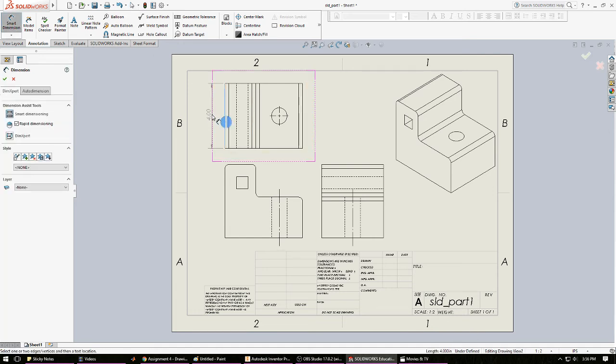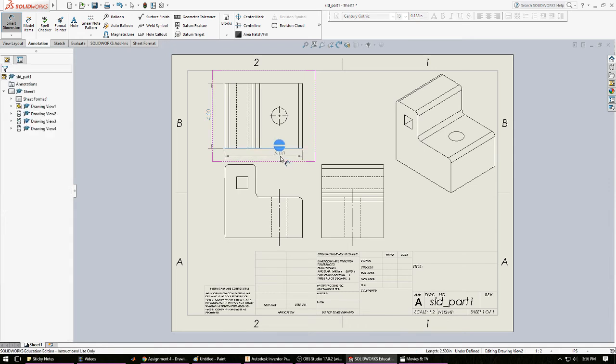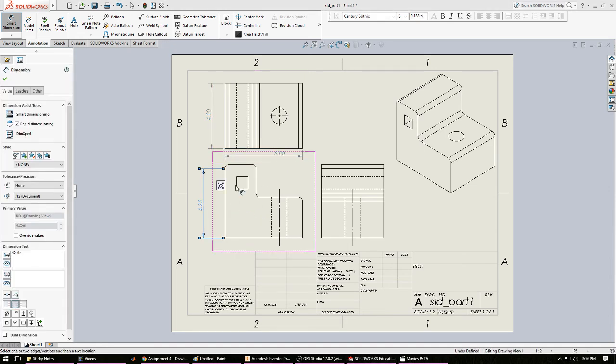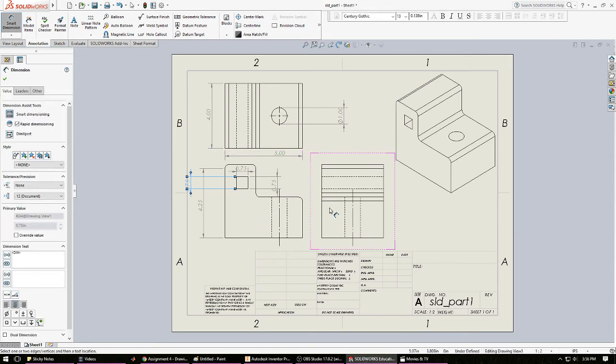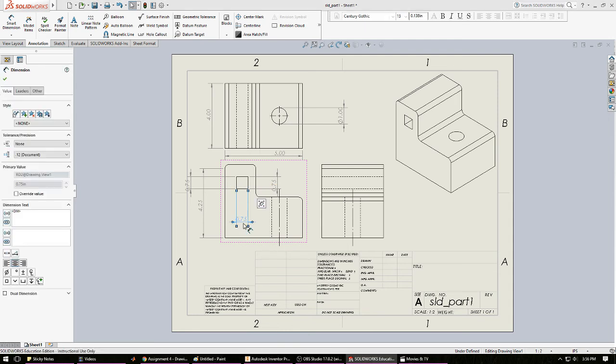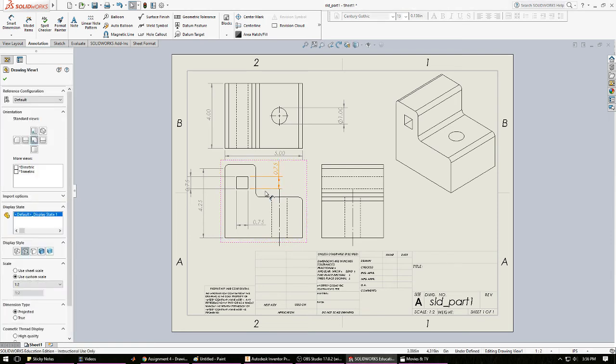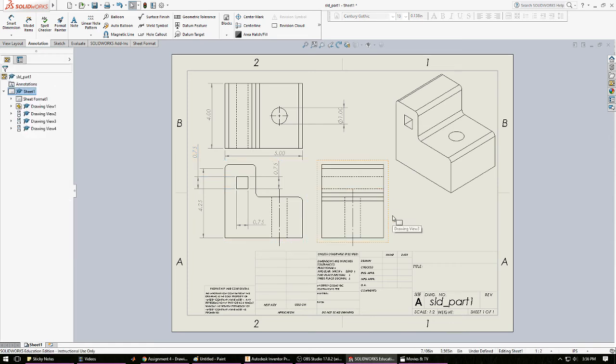So you just click Smart Dimension and you start adding stuff in. You can do overall height, length and width. You can add all these things in that we would expect you to do. Something like this. Obviously, I'm putting them in ugly locations. One thing about this is presentation is key. If this looks ugly, if things intersect, then you're doing it wrong, because the whole point of these drawings is that they look nice because they are a good representation of the CAD work that you have been doing. So make sure that you add dimensions until this says fully defined.